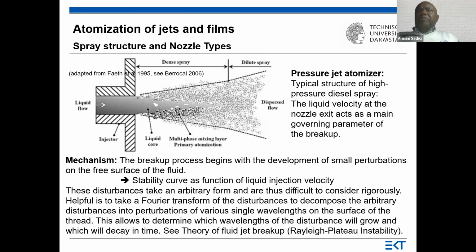And the liquid breakup length depends on whether we are in the primary breakup or in the secondary breakup. So in liquid jet atomization, is the disturbance coming from the nozzle itself or from shearing with the ambient? These may be both. It depends on the quality of your nozzle.